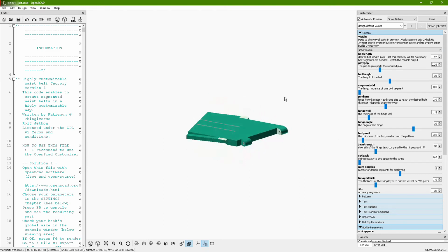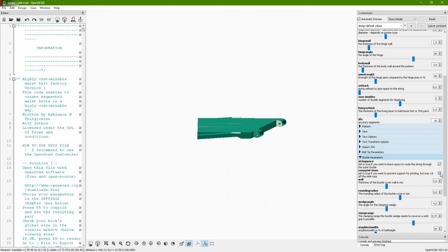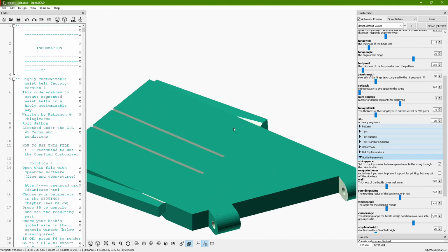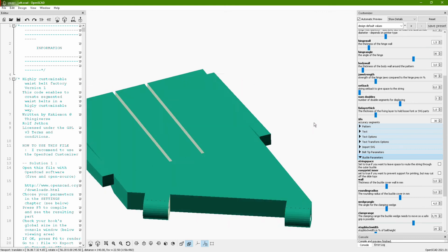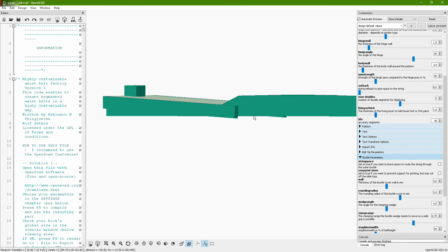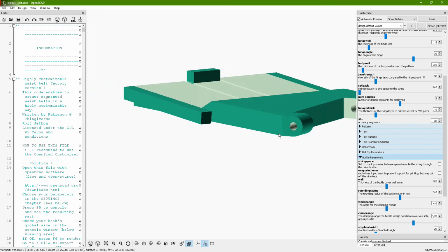And on the inner buckle, when you look here, because you want to print it on this side, usually on an FDM printer, because theoretically, if you have a different kind of printer, you can print it the full size, with everything. So now you see these guides here, they go even a little bit up here, and you can see even this one is, by the way, the string space. This cutting off from the string space does that also. If you remove that, you don't have it at all, but it's exceeding this part, and printing it this way on an FDM printer would mean you have to put some support underneath, which you probably don't like because that's a lot of work to remove it afterwards.